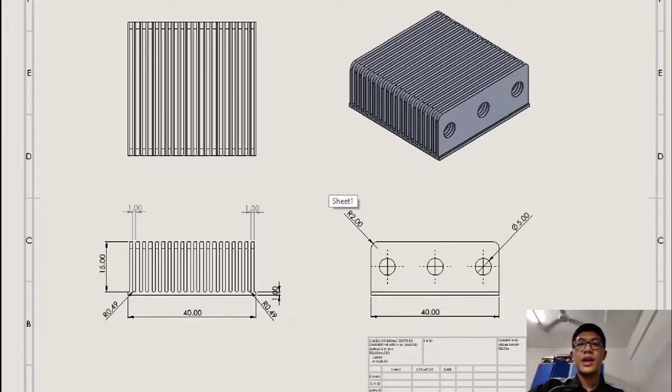B0920100144. And now I'm going to present about the design of our heat sinks. For design number 1, which is the hot fin, we have a heat sink that has a 40mm times 40mm base and 16mm of height, where the fin height is only 15mm and the thickness of the base is 1mm.